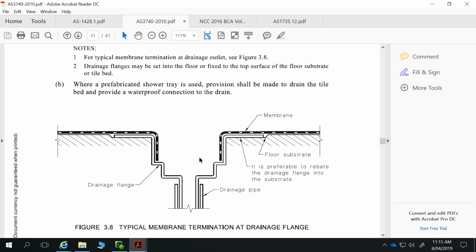What you have to do when you start getting larger bathrooms is that you have to have a floor trap, and then also a shower trap as well, because when you're dealing with a 1 in 80 slope to your main bathroom that transitions to a 1 in 60 slope, you end up going through a lot of height.